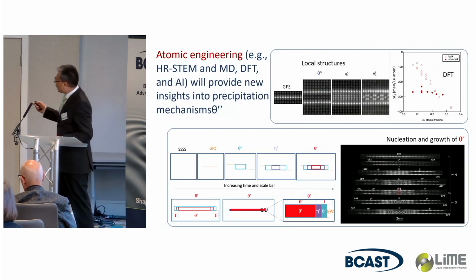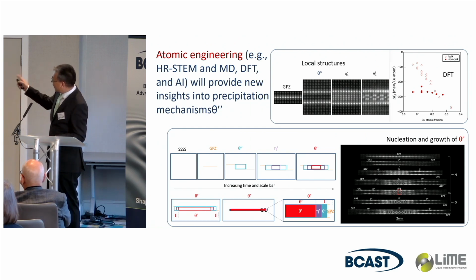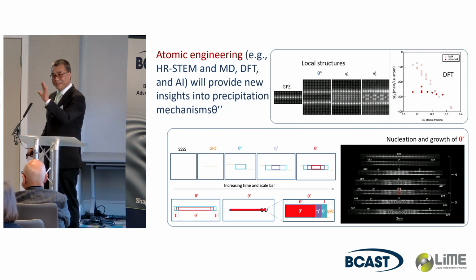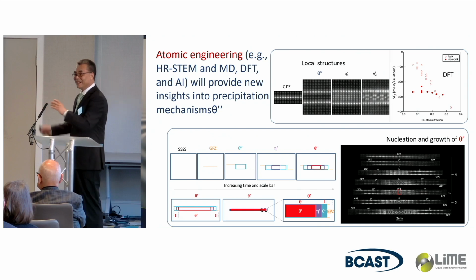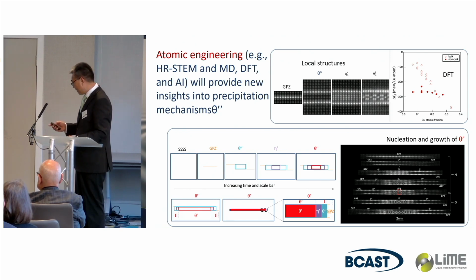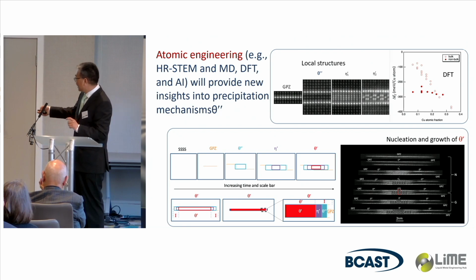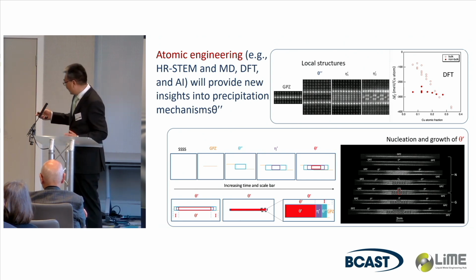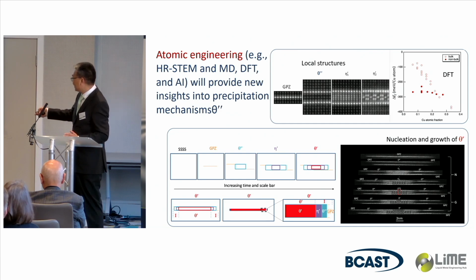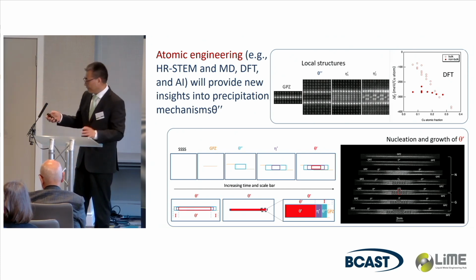And of course, we found out earlier what we had learned: in aluminum copper, you get a GP zone, theta double prime, theta prime and theta, all this precipitation sequence. Then we found out recently they are not like that. They are more like a process, illustrated here. You get a GP zone, all this nucleation process, and then you get theta prime, a local structure, and I get a theta nucleation in the middle of theta prime. You get the first initial structure of theta prime, and theta prime can grow by advancing this interface. The whole lot here becomes interface. The interface is theta, theta prime, theta double prime, GP zone, rather than sequential to have all this.